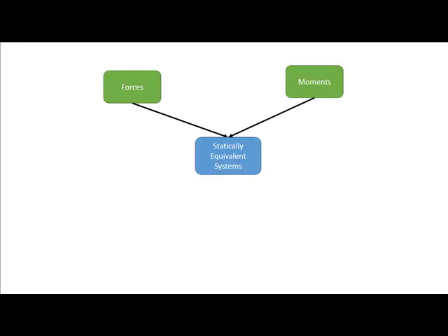So what do we do with sets of forces that are statically equivalent? We've got two ways that we build on this idea. The first, we're going to work on simplifying systems. Before that, we want to talk about what's known as the resolution of a force into a force and a couple. So any force, if we want to find a statically equivalent version of that in a different location, we can use this process.